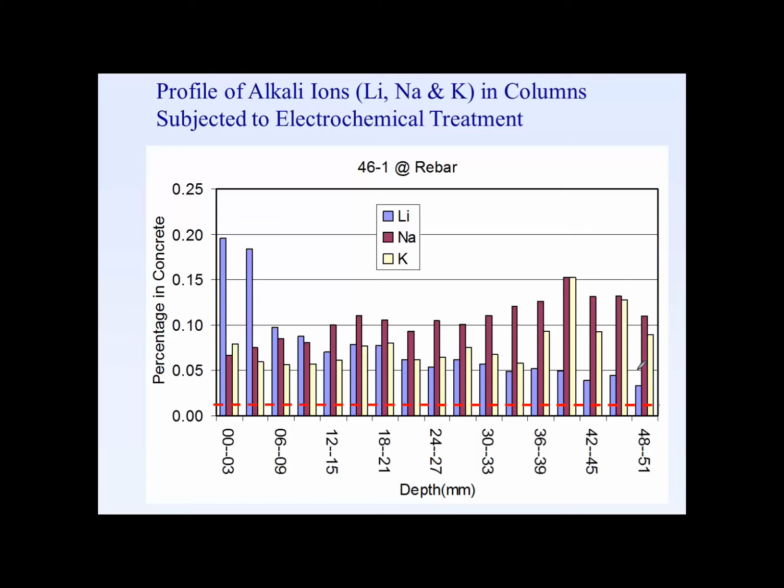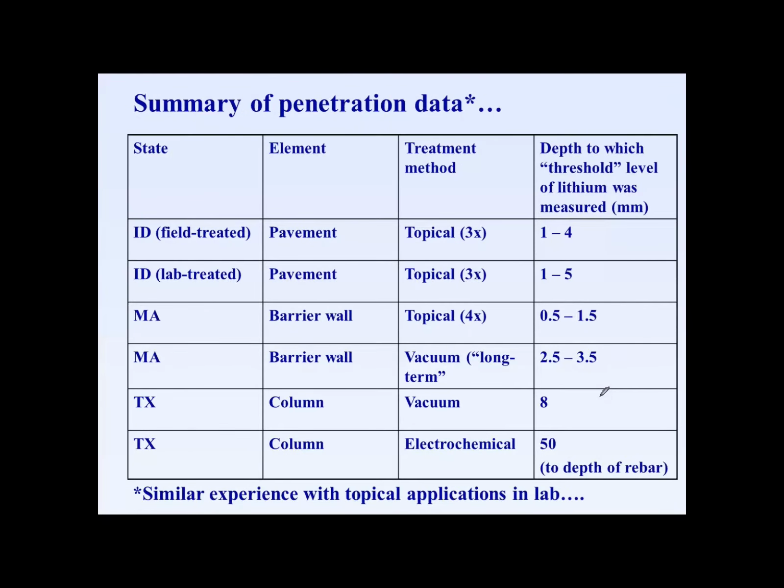We don't have enough data really to give any firm guidance on it, but certainly a word of caution at this point that we do need to first determine whether or not there will be any detrimental effects of the increase in sodium potassium concentration, which may outweigh any increase in the lithium concentration. But in terms of driving lithium into concrete, I think we do have some very good evidence here that electrochemical methods can be used. But again, we just have to be careful about this redistribution of internal alkalis.